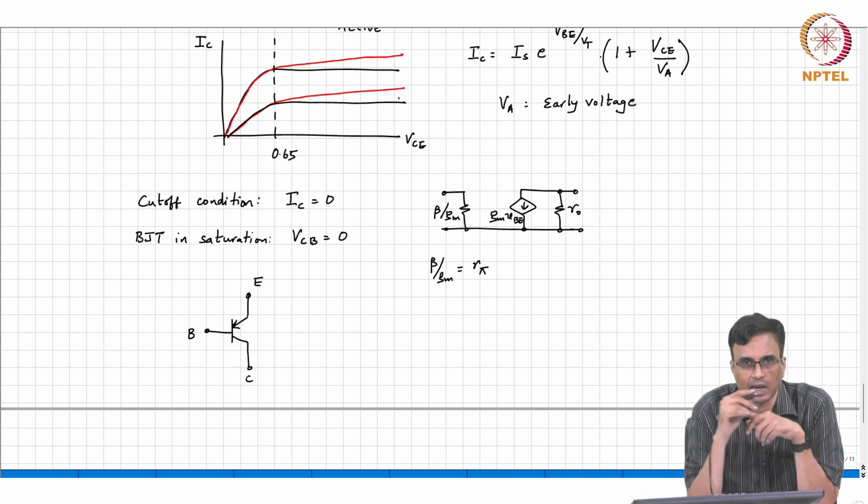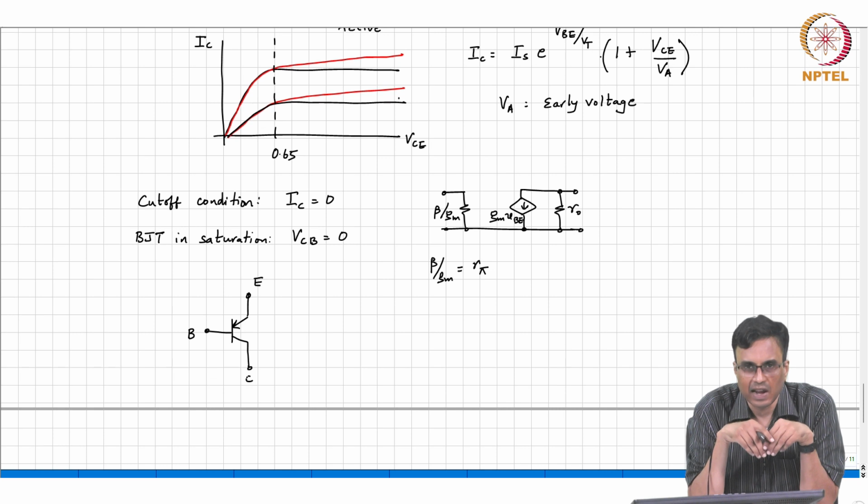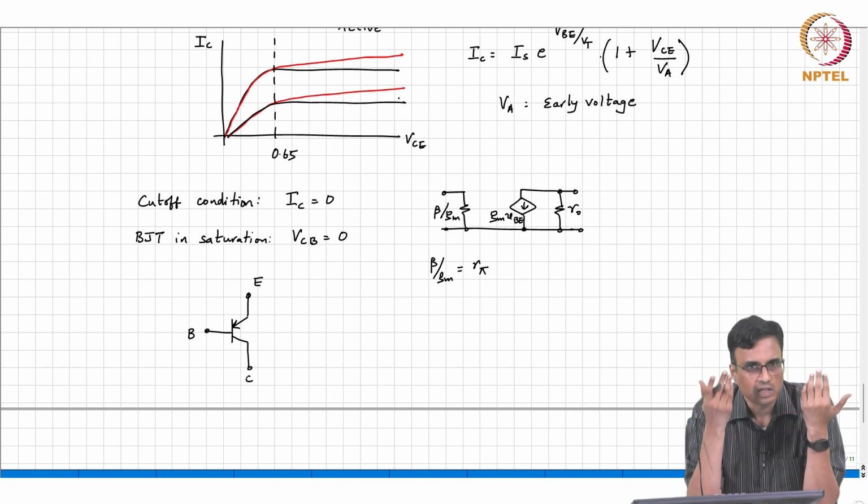Just like how an NMOS circuit can be turned into a PMOS circuit, all we do is first set VDD to minus VDD, then add VDD to all nodes. Likewise, to convert an NPN circuit into a PNP one, you change VDD to minus VDD, and we do not like negative potential, so we add VDD to all nodes.